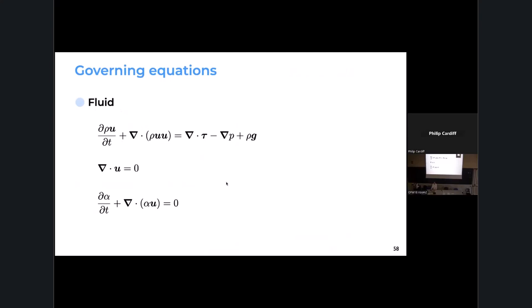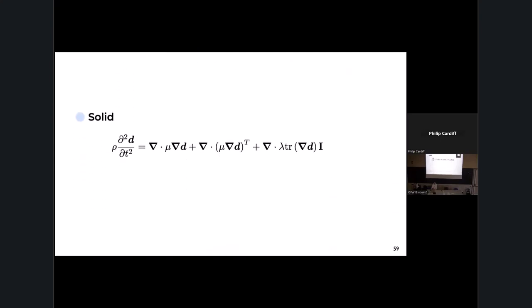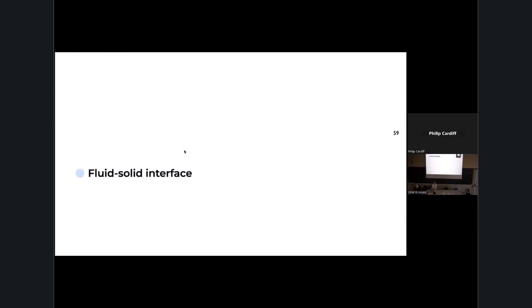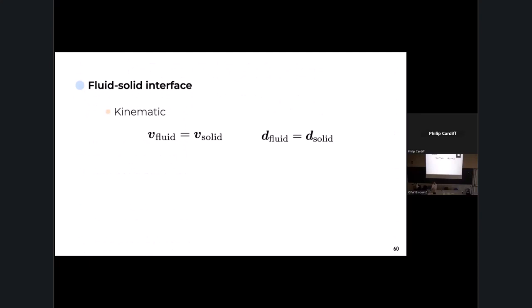So the fluid, this is the interFoam or interDyMFoam. So Navier-Stokes equations on the volume of fluid, conservation of this alpha field. The solid solver is just a dynamic version of linear elastic in this test case, even though it could be a nonlinear version. And then we have these extra FSI interface